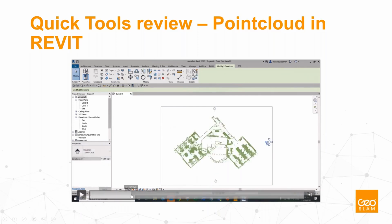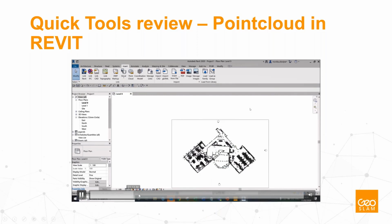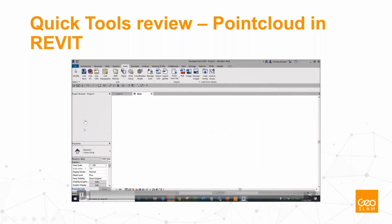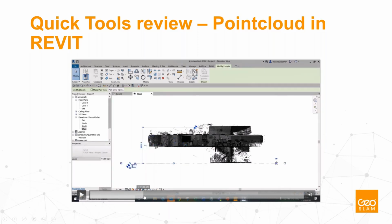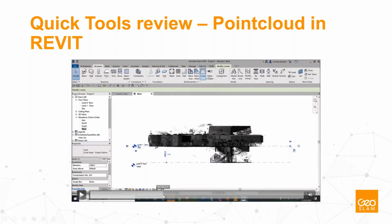So there are as well, depending on what template you have selected, you can choose the north, south, and west views. And then automatically Revit creates two levels, 0 and 1, which you can edit and put where you like. In this case, I'm creating a couple of levels and defining them as floors.